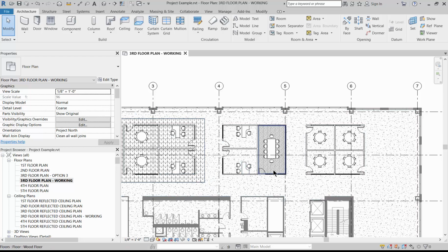But again, when you have half-inch or especially anything higher than that, keep in mind that you'll need to transition it with some kind of a slope, and that will require the transition space. So having a wall around it allows you to only transition at the door. So this is just a basic way how we could show some of the different flooring types through the color and pattern.